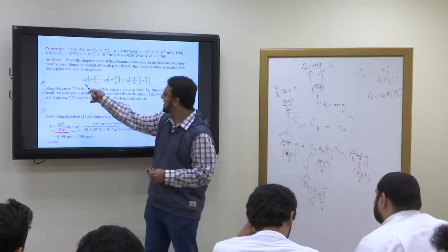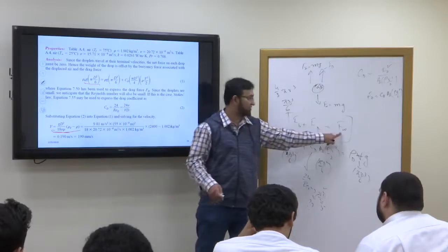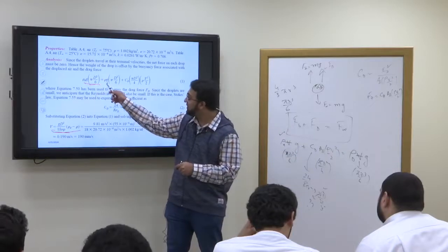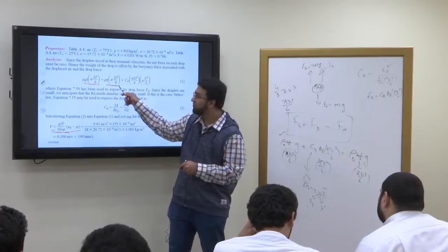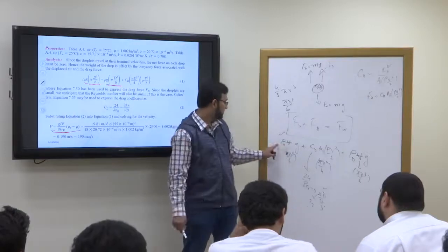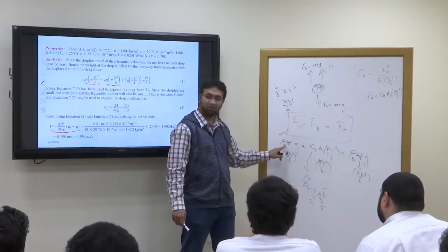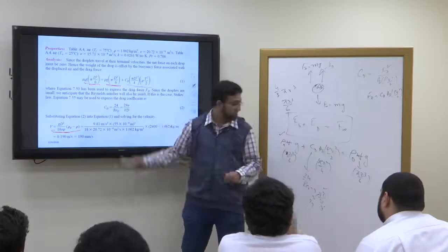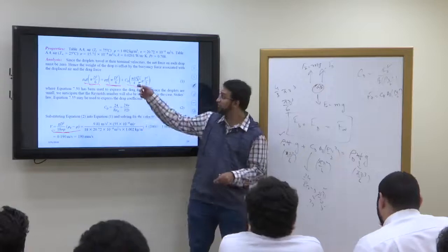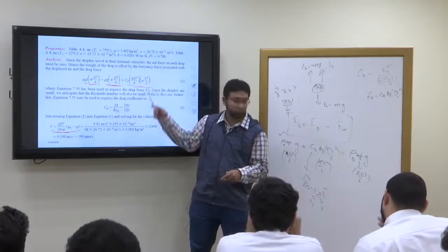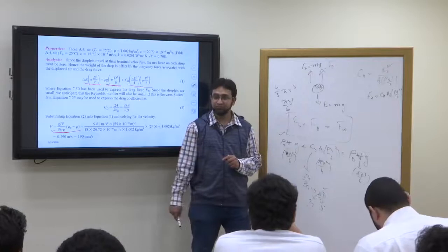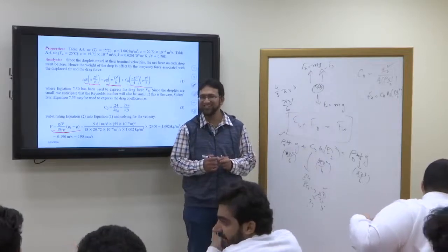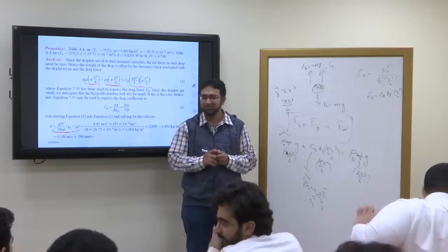You see, this is F weight, equals buoyancy force, rho g V, volume, buoyancy force, plus CD AF, AF is pi d square by 4, into rho V square upon 2. Rho of the water and rho of the air. Water? There is no water here, not water, I mean the other droplet, which is the ink here.